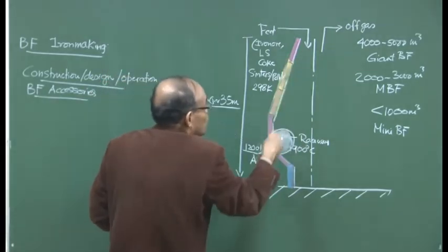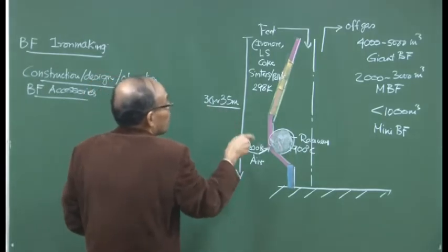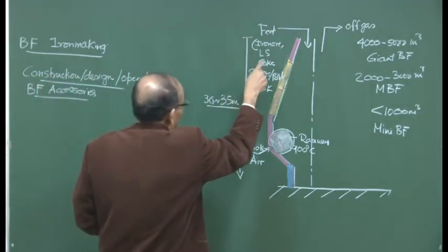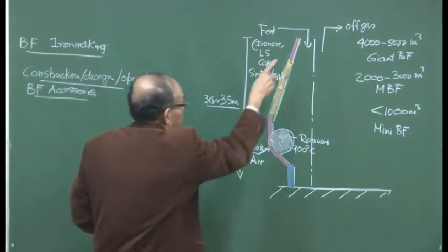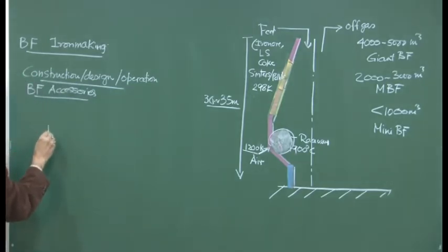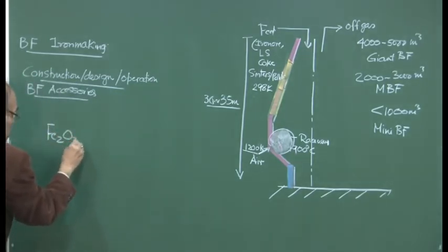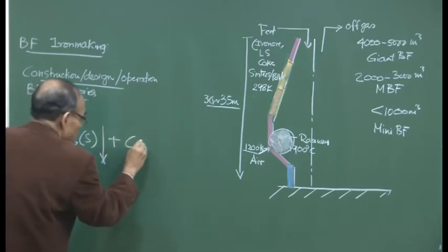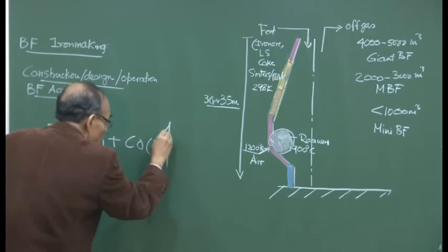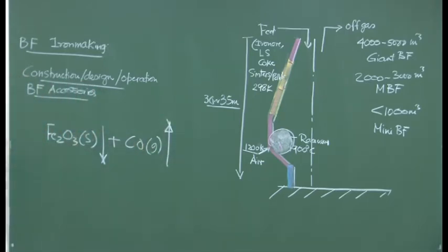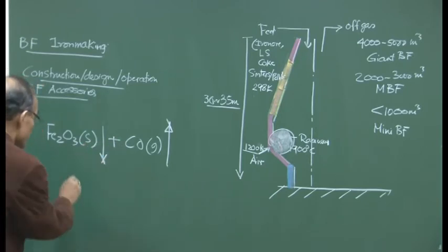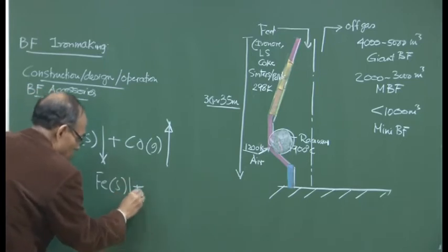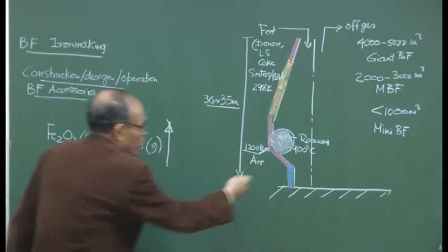As it rises up, it will have more tendency to get oxygen, and from where it will get oxygen, but from iron ore, where oxygen is relatively loosely bound, rather than from limestone. As a result, the iron ore gets reduced. The iron ore which descends as a solid particle within the furnace and the carbon monoxide which ascends within the furnace react with each other. Somewhere they are going to meet, and the net result is the production of solid iron and carbon dioxide, which goes down. Of course, because the charge is moving, we are continuously taking out.